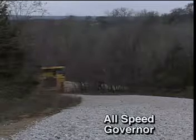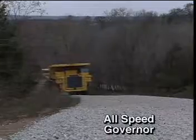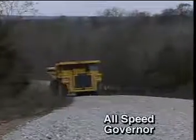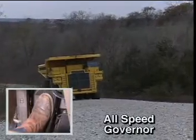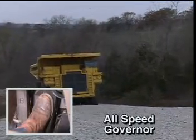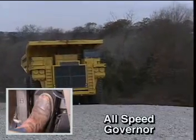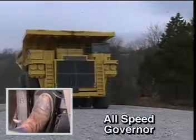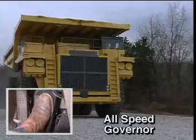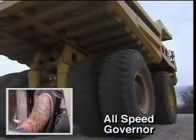An all-speed or variable speed governor provides aggressive speed holding capability, and small changes in accelerator position result in large gains in torque. This type of governor attempts to maintain a constant engine speed for a given accelerator position. The all-speed governing mode varies engine speed based solely on input from the accelerator position sensor. This governor attempts to hold engine speed constant when the accelerator is held in any position between minimum and maximum RPM and engine load is varying.